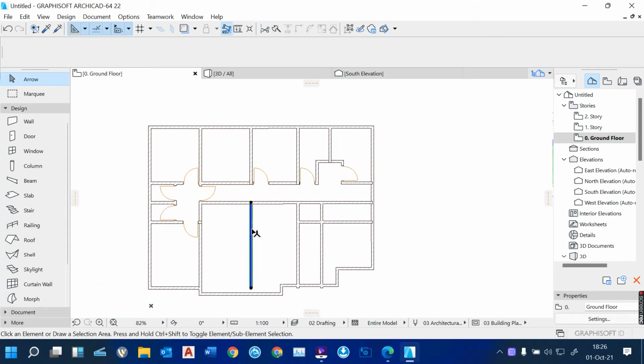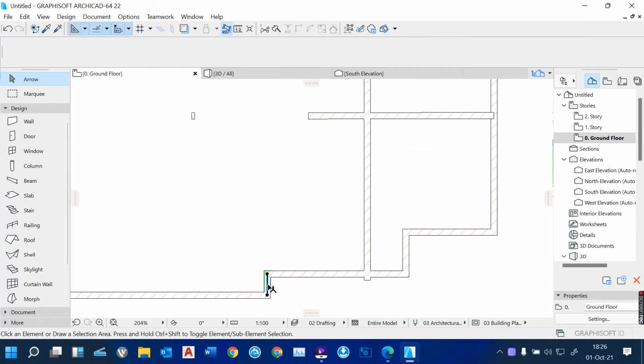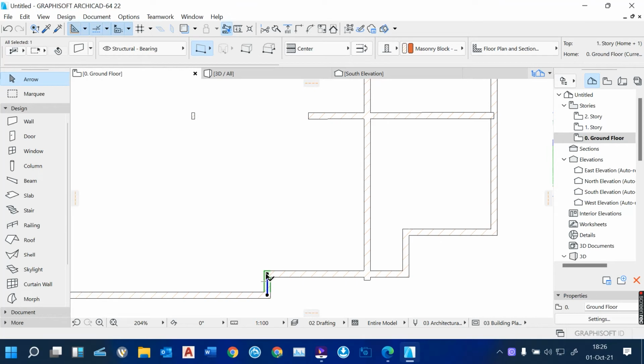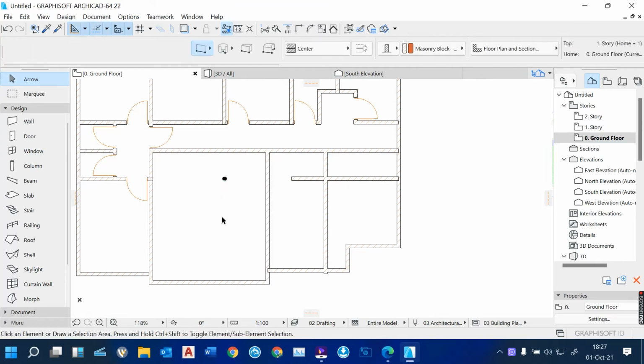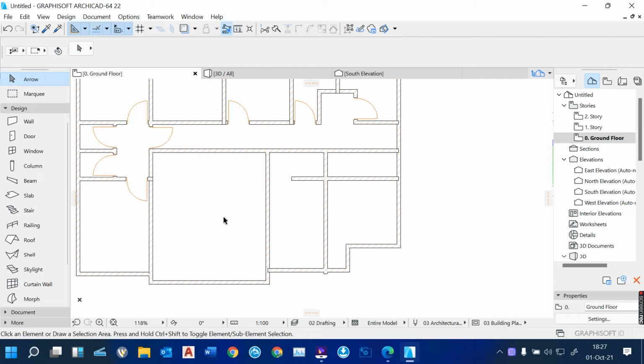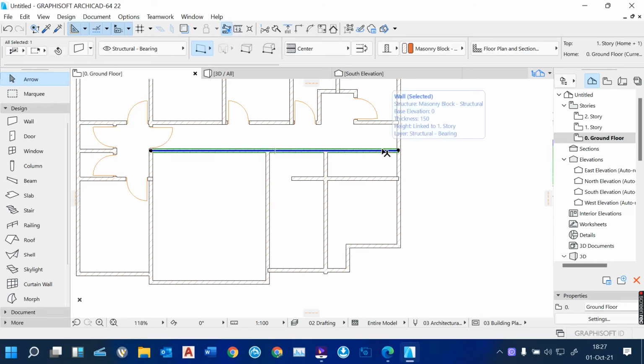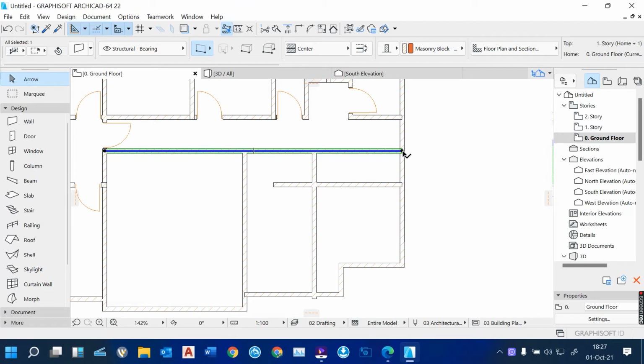These ones I can now delete, by just clicking and then you delete. And then I can delete this as well, because I don't need it. Then I can stretch this wall to join with this. There, just stretching. Can delete that right now. So I've gotten that shape. So when I come down here, there's another opening for that, which I simply stretch.